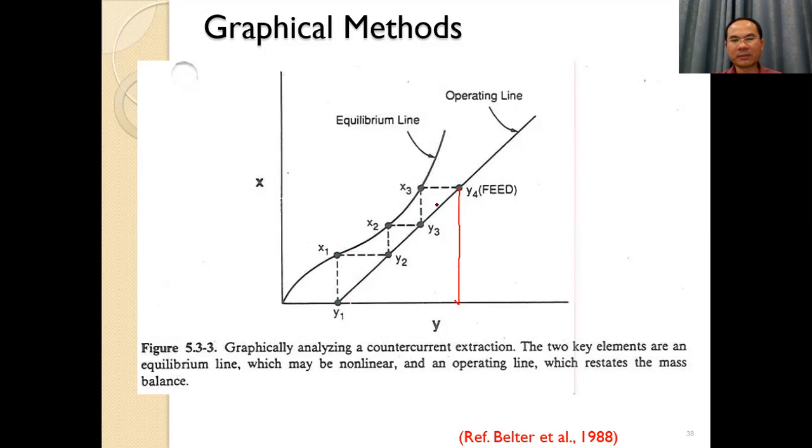It is 1, 2, 3. Let's add the 3 steps. And sometimes you can write, if you know y5, that's right. y5, you can construct like this. Okay, this equilibrium line, it's approximately 1, 2, 3, about 4.7 or 4.8. If you would like to get to 5, it's maybe like this. But this is about 4.5 steps, but you can round up to 5 steps. That's it, 5 steps for this case.